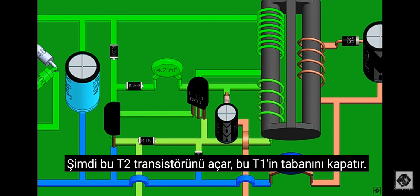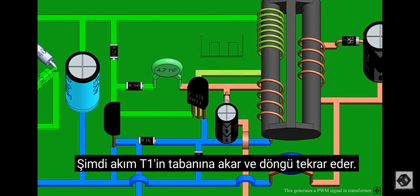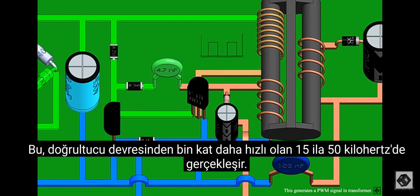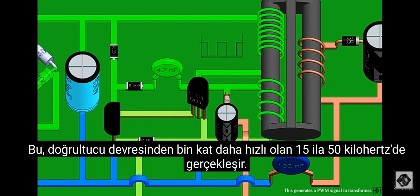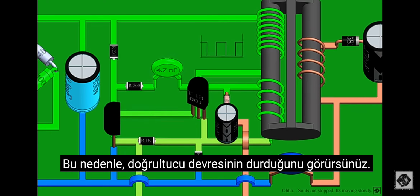Now, this turns on the transistor T2. This shunts the base of T1, turning it off. As T1 turns off, the flow of current to T2 is cut off. Now the current flows to the base of T1 and the cycle repeats. This happens at 15 to 50 kHz, which is 1000 times faster than the rectifier circuit. Hence, you would see that the rectifier circuit is stopped.